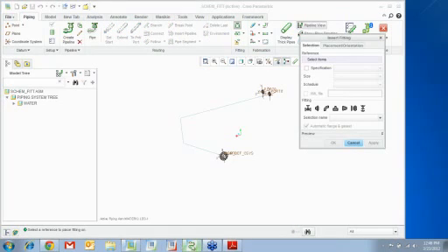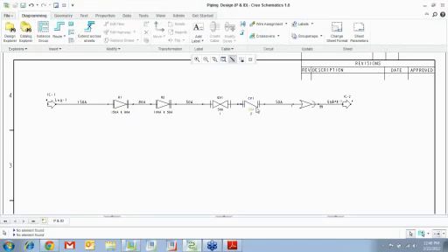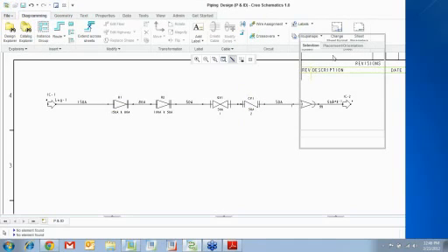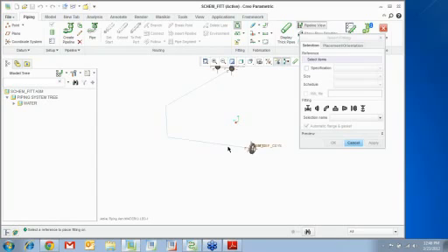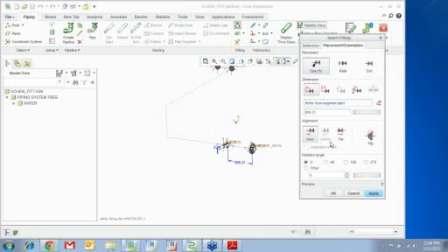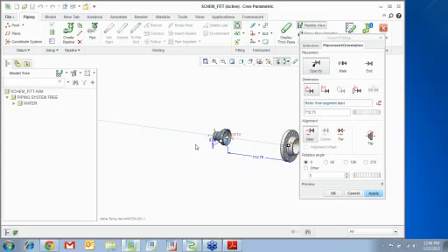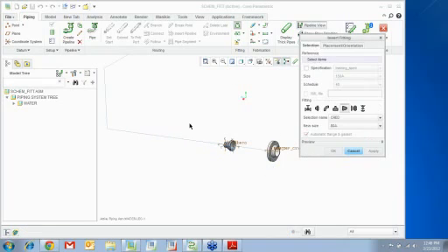So let's see the order of the fittings also in here. Reducer, gate valve, check valve. Okay. So note that I'm not picking anything from here. All I do is I go click. It defaults to the reducer and it picks the right size for me. See that? When I go to placement, you can see that. You can move it around. Okay. You can hit apply.